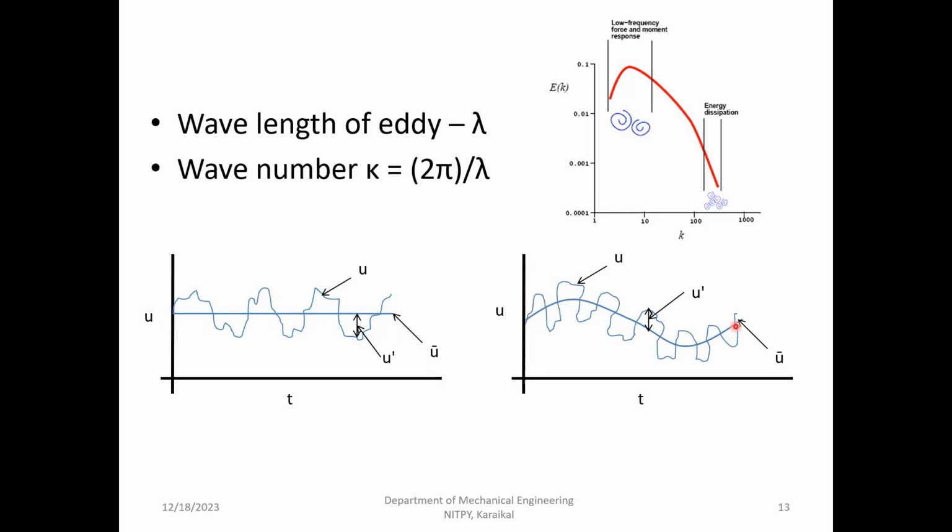When vortices roll up behind a bluff body, like a square or cylinder, you can have rolling up in the clockwise direction and then in the anti-clockwise direction. So velocity itself will be fluctuating over time. Now comes the difficulty. If I want to capture this velocity fluctuation, my computational mesh size must be really small, and the time step must also be really small. I must look in micrometers and time steps of nanoseconds.